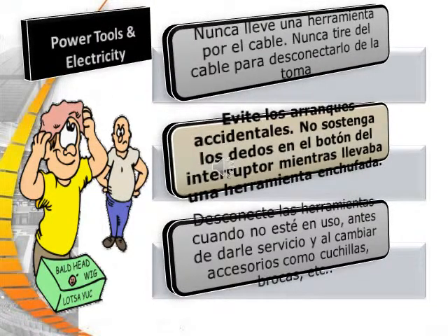Never carry a tool by the cord and never yank a cord to disconnect it from a receptacle. Avoid accidental starting by not holding your fingers on the switch button when carrying a plugged-in tool. Disconnect the tools when not in use, before servicing, and when changing accessories such as blades or bits.